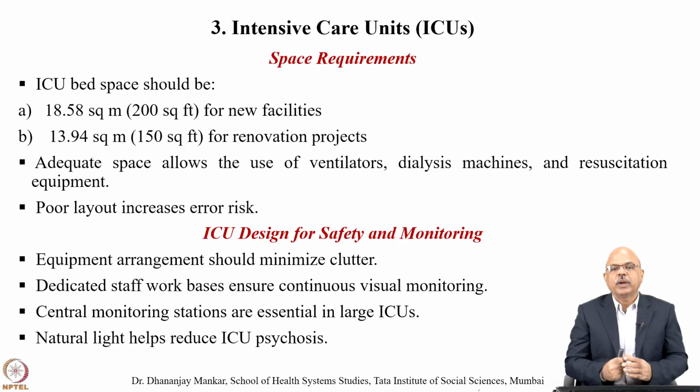Now, with respect to intensive care units, why do space requirements and design play a major role in safety? As you know, ICU bed space should be 18.58 square meters, that is 200 square feet, for new facilities, and 13.94 square meters, that is 150 square feet, for renovation projects.